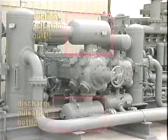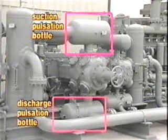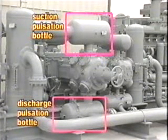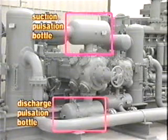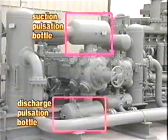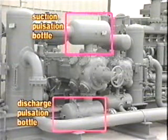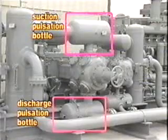These are called pulsation bottles. They are used to reduce pulsation in gas pressure caused by the reciprocating movement of the piston. The bottles, mounted on the suction and discharge sides of the cylinder, help reduce gas pressure fluctuations through the compressor, lowering the damage and wear caused by excessive vibration.